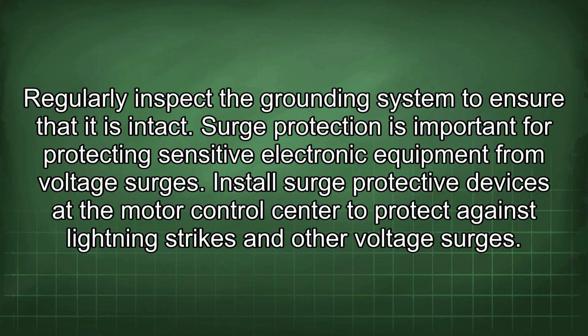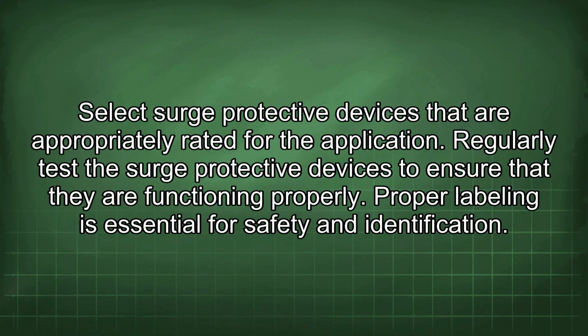Surge protection is important for protecting sensitive electronic equipment from voltage surges. Install surge protective devices at the motor control center to protect against lightning strikes and other voltage surges. Select surge protective devices that are appropriately rated for the application. Regularly test the surge protective devices to ensure that they are functioning properly.